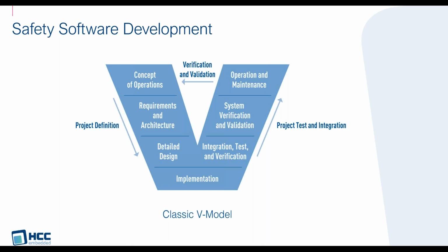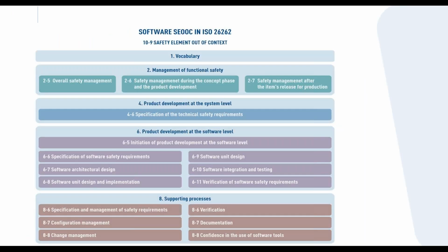So starting from this premise, we've researched many of the standards. And the one that we came down to as the best working reference for building a reusable software component was ISO 26262, the automotive standard for building a vehicle. And it specifies how to build what they call SEooC, safety elements out of context. These may be hardware, like a microcontroller or resistor, some component you put into a car that wasn't designed originally for a car, or it could be pieces of software, and that's what we call a software SEooC. Software safety element out of context.